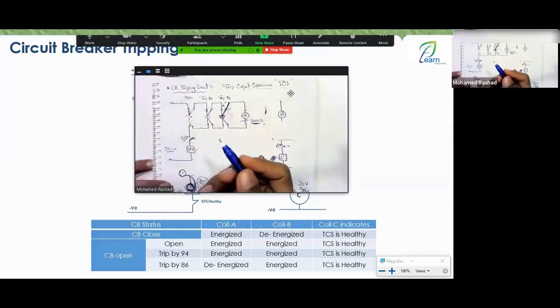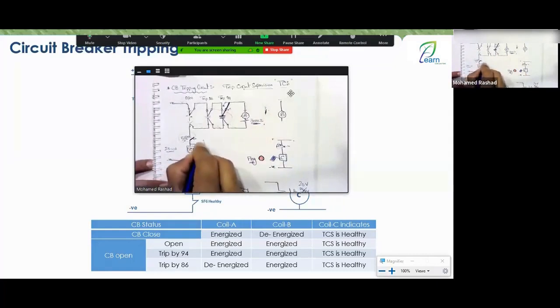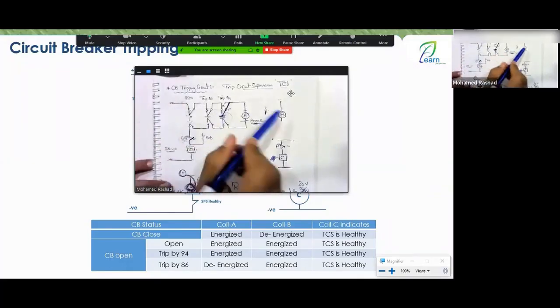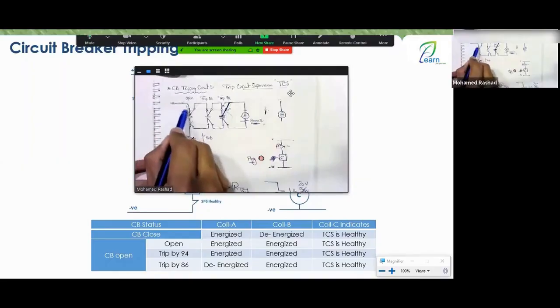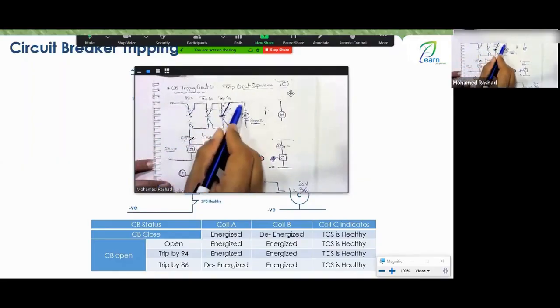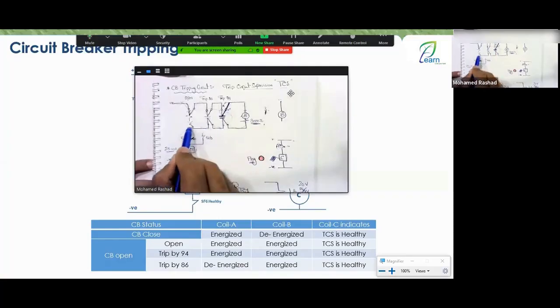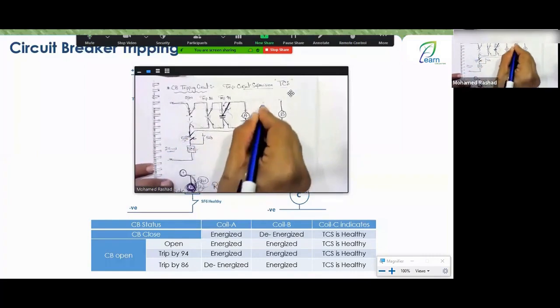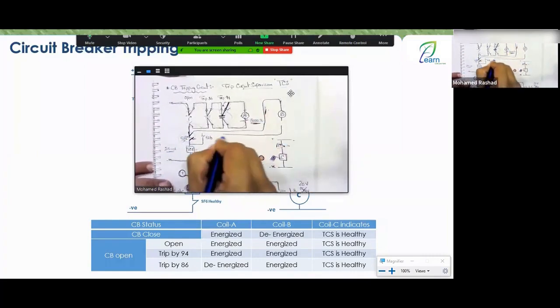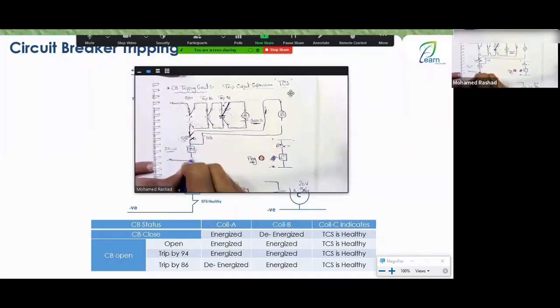He said that if the breaker is open, then here you use a normally closed contact called 52B. If the breaker is closed, this is closed and that is open. When the breaker opens, this returns to normally open and that returns to normally closed as it was. That's great. So he said, I also want to monitor this. How will I monitor it? I want to monitor all this wire here. Just keep going until I reach this point. Isn't this open now? I'll come from the top of this contact and go here to coil B, and then I return from coil B to the 52B and then back here to the trip coil.